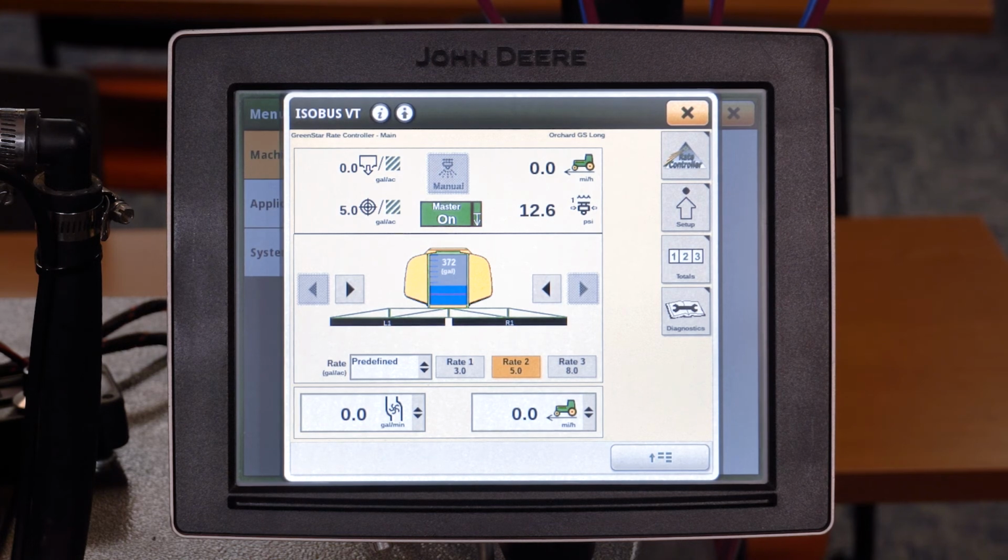If the system is pumping and liquid is flowing, but the screen doesn't see or show the flow, there is a problem with the flow meter or with the signal getting from the flow meter to the display. This calls for checking the voltages at the flow meter and doing a tap test to confirm that the harnessing is good. A lot of calls may start with, my pump quit, but there may be a lot more to it than that.